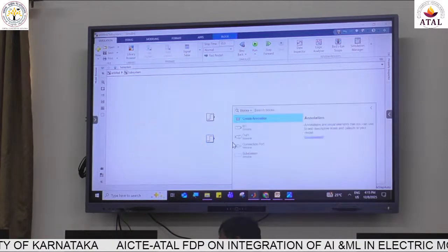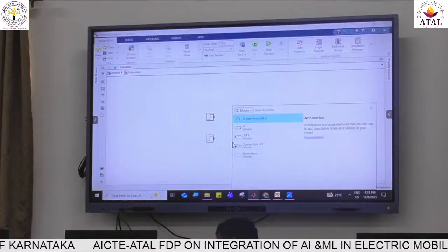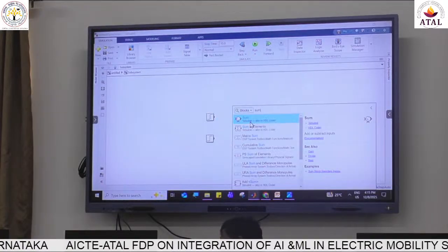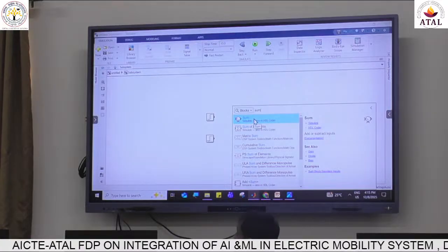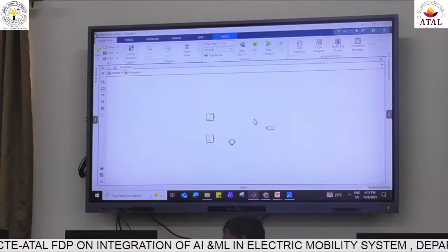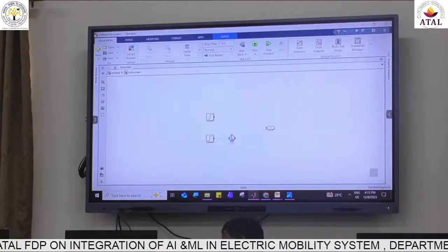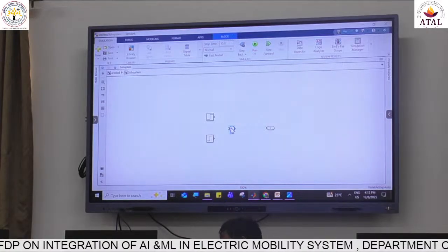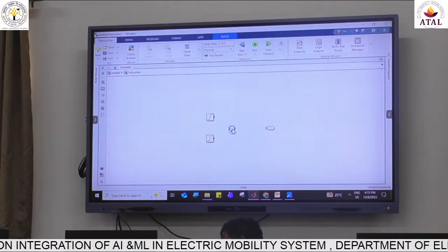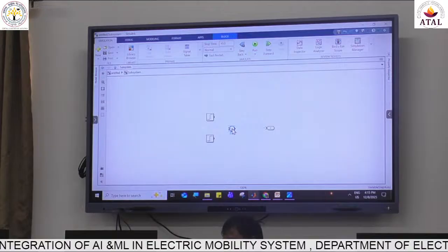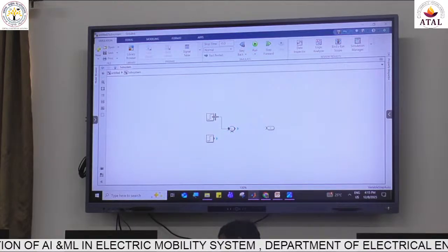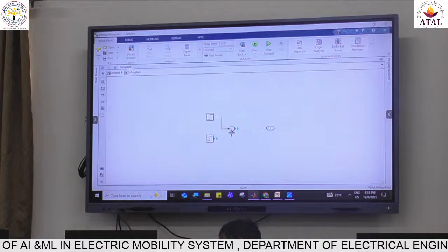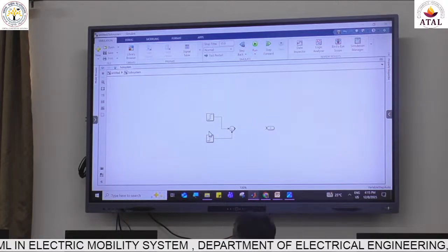And then to add up both the signals, I will use a summation block. Add block or sum block, you remember, both the components are one and the same. So let me use the sum block this time to show you it works one and the same. It doesn't matter. It's the same block. You'll see plus plus is there. If you want to make it plus minus, I can do that. But right now I don't want to do plus minus. I want to do summation only. Whatever component parameters are there, I will update inside this step block.